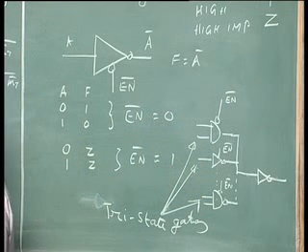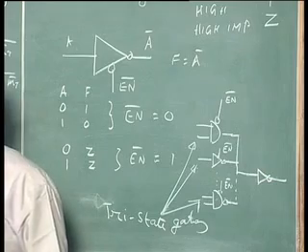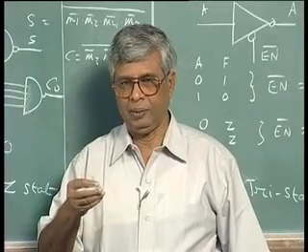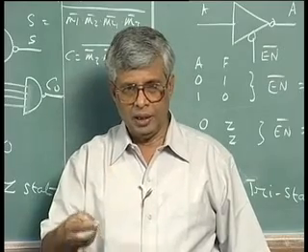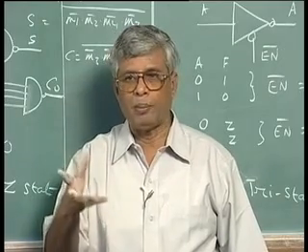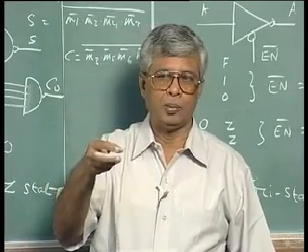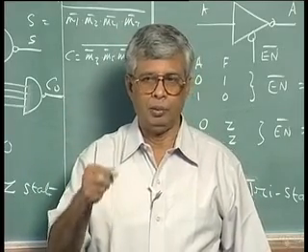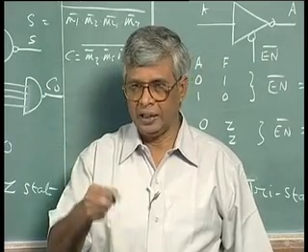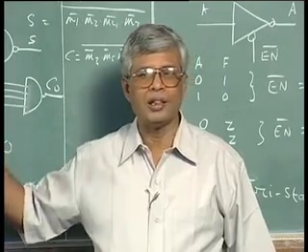The next step we will take is towards LSIs, large scale integrated circuits, and they have to be programmable, as I said, because when you have larger and larger circuits, they should be useful more and more. I cannot make a simple circuit which is mappable or not mappable, so I just throw it and get another circuit. When I make a large scale integrated circuit, it should be available for many operations, so they become programmable. We will talk about it, but before that I want to mention that MSI is not restricted to only combinational logic circuits.